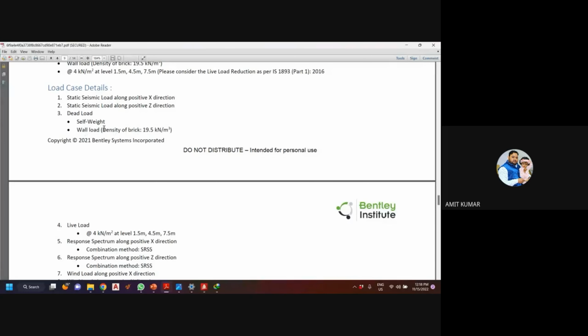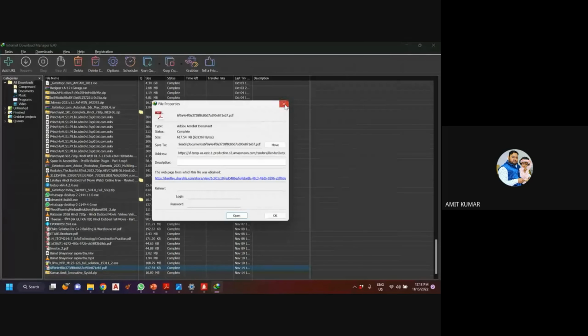And let me show you how to calculate the wall load. Here it is, I just provide the wall. Okay, how to calculate the wall load? Here it is, we have the density of brick here. Like in our previous project, I put the value 20 kilonewton per meter cube. Okay, I just assume it the 20 kilonewton. So all these things, sometimes it will be given, or if you don't have this data, just provide the maximum data value, because if your structure is safe for the maximum data, then it will be safe for any other data also.